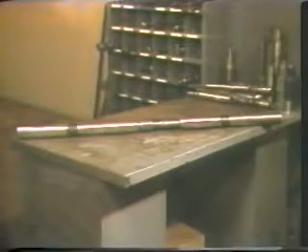Another device that can be set across the sleeve allows communication between the tubing and casing while plugging the tubing area beneath the sleeve. This device is called a separation tool. A pack-off is used to patch an internal tubing leak to allow the well to be produced until the tubing can be pulled and replaced. Pack-offs are run and retrieved using wireline methods. The pack-off consists of two sealing elements which are attached to either end of a spacer pipe. When run in the well, these two elements straddle the hole in the tubing and seal on the ID of the tubing. The seals on the elements are mechanically expanded against the tubing wall when the pack-off is set.